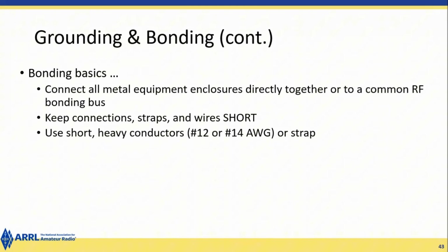A. What is a possible cause of high voltage that produces RF burns? Ground wire has a high impedance on that frequency. What is a possible effect of a resonant ground connection? Yep, the RF voltage can flow on the enclosures of the equipment itself.